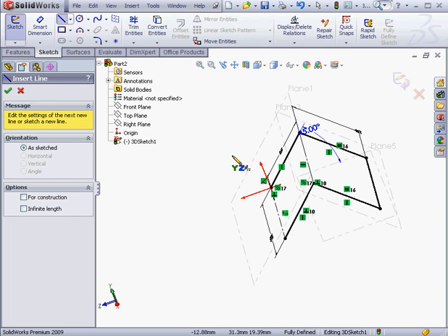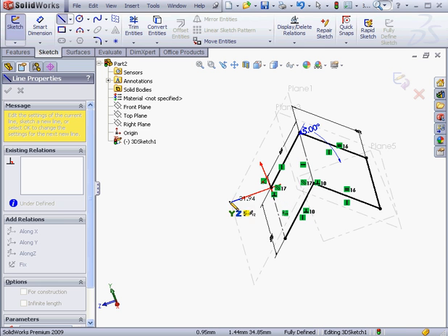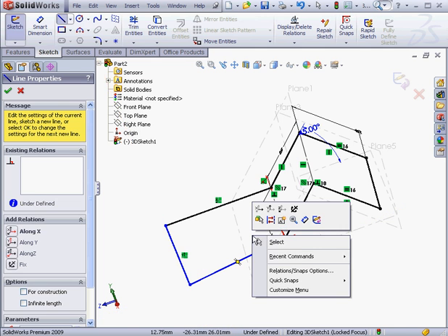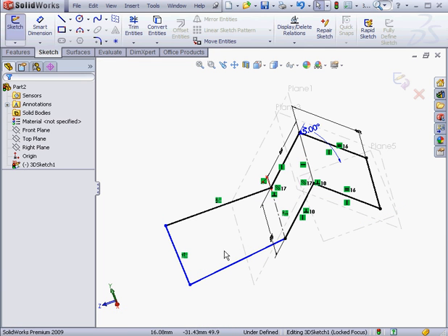Let's create a few more lines now. Let's create one along the Z-axis. Saying Z-axis sounds weird, that's why I say Z. I'm going to show you a common mistake here. I want to show you how to recover from a very common boo-boo. What I'm trying to do is create a line along the x-axis, but I forgot to click the Tab key to switch planes. Let's right-click and select End our line sequence.